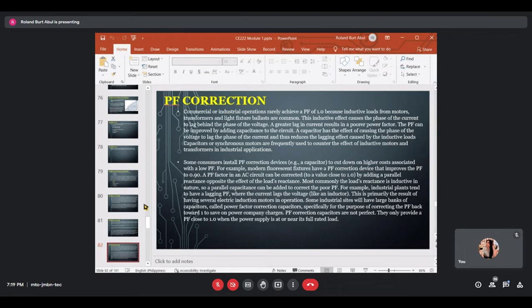A low PF is caused by electrical circuits having a greater amount of inductive loads such as conveyors, compressors, grinders, HVAC systems, machining equipment, welders, and etc. Industrial and commercial electric customers operate with system PFs between 0.75 and 0.98. A PF for a building system below about 0.95 is considered low.